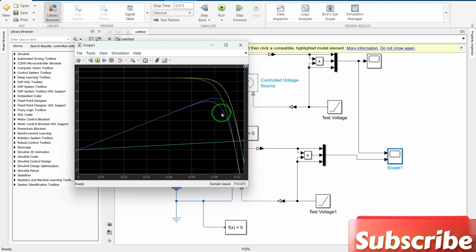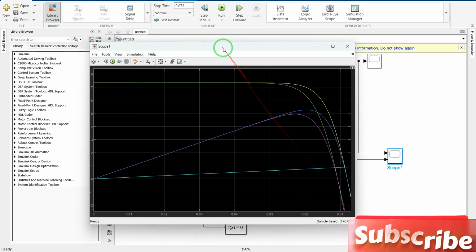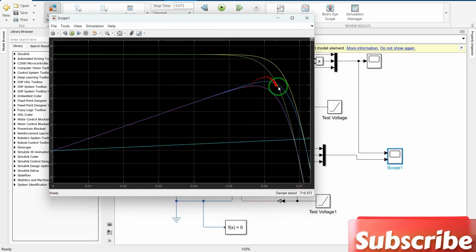So as you notice, temperature is so important, and it affects the power and efficiency of our cells, as it is obvious here. With the same voltage rate, here in our time domain, you can see that the power will be higher when the temperature is lower or in its proper area.